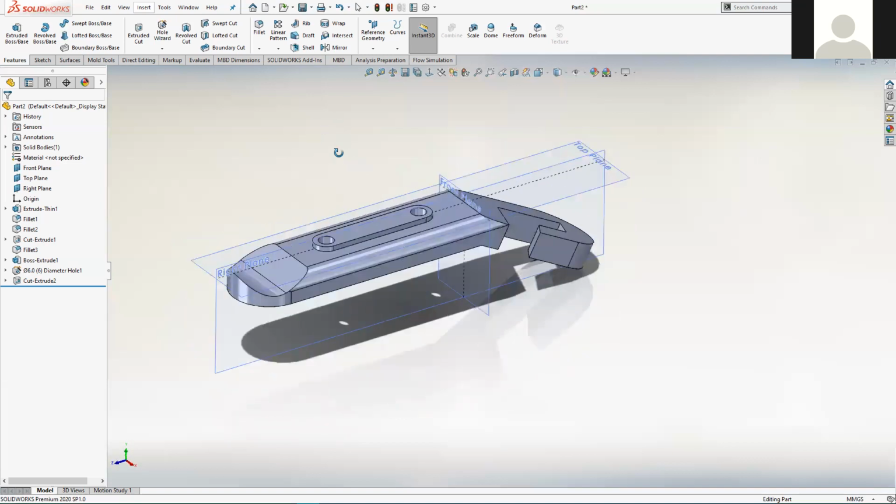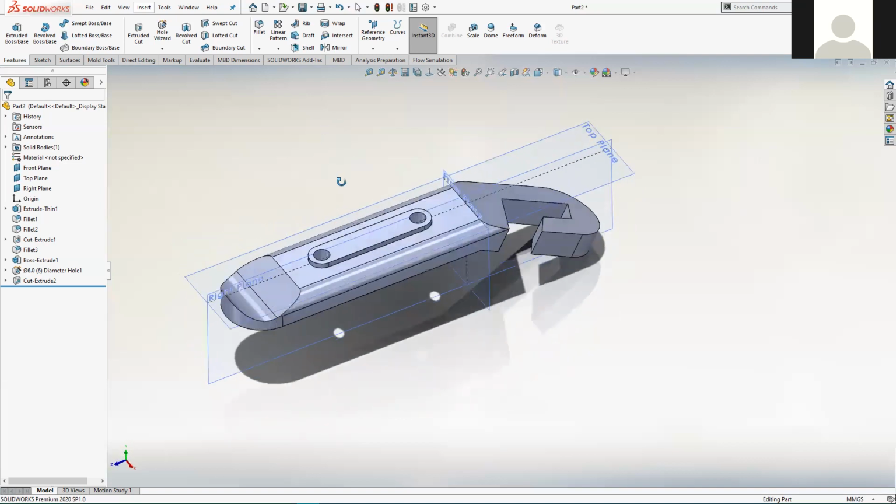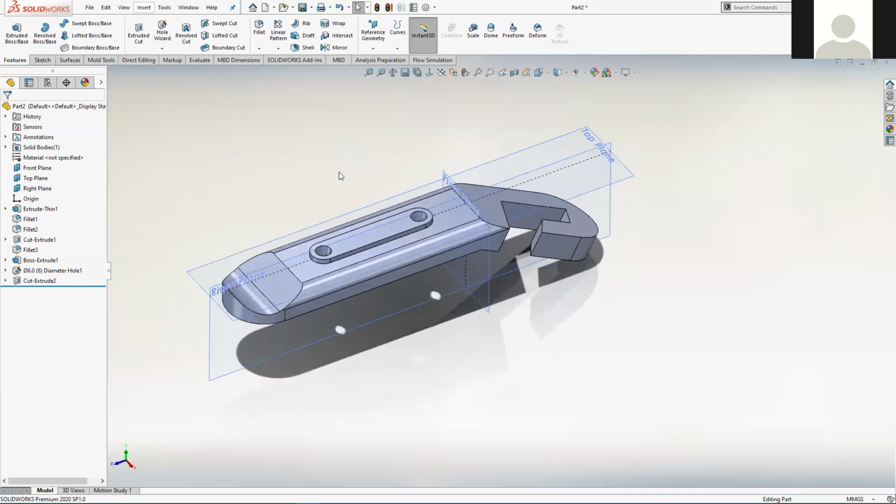The second word of warning there is, if you are going to create part drawings that are of parts, keep the drawing and the part in the same folder. It just simplifies everything. It's not 100% necessary. You can set SolidWorks up so that all your parts sit in a certain folder and then all your drawings sit in another folder.